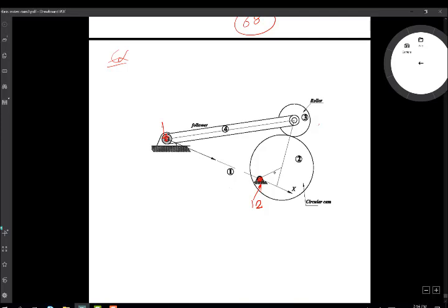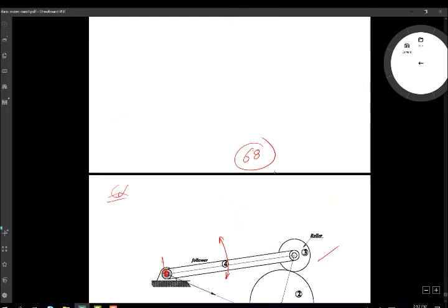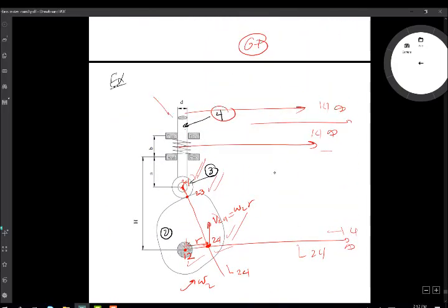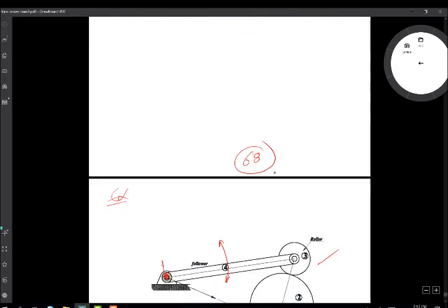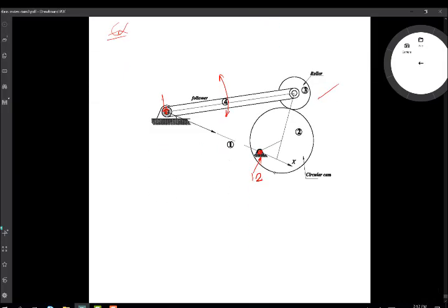That's a roller follower also, except the follower rotates or oscillates as opposed to translates. So not a translating follower, it's the rotating follower. So this follower here does pure rotation, if you remember, as opposed to another follower like this one, which does pure translation. It's like pure sliding, and this one rotates, and this is a pole of this follower, so it's point 1, 4.